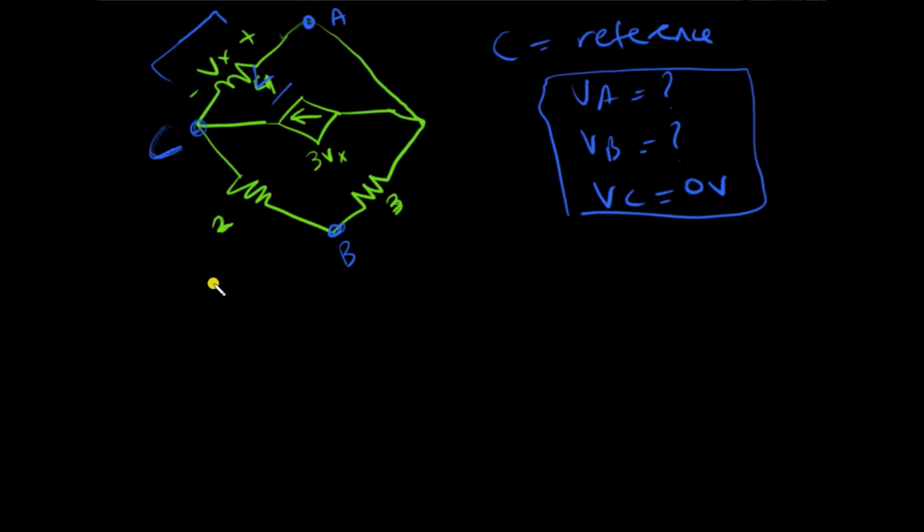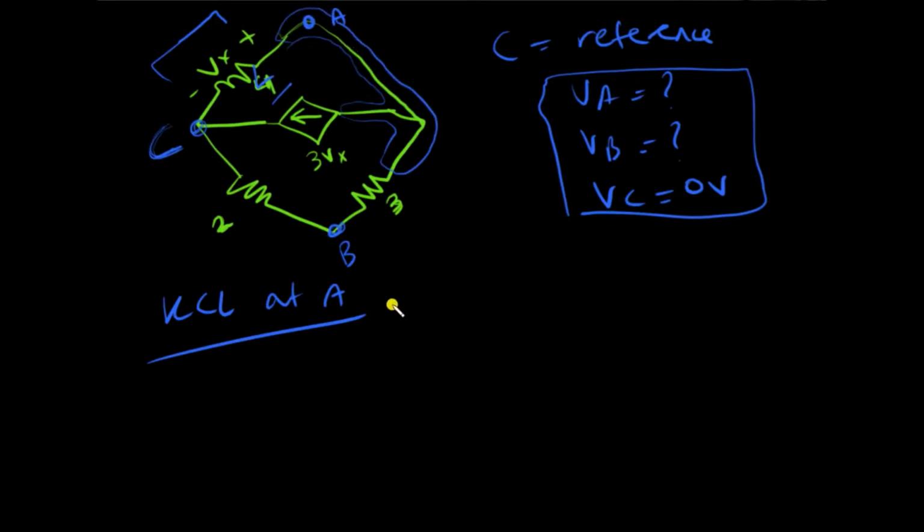So I'll start writing the nodal voltages at all nodes. So VA, one thing to note is that VA stretches from this entire area. All of this is VA. So it is very important to take into consideration all the branches when you're writing the KCL.